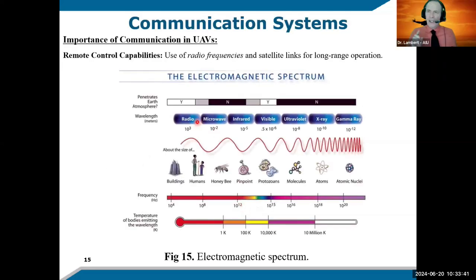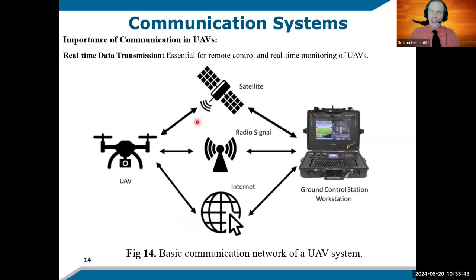Abdullah, a question. How much energy does it take to actually communicate by remote? Well, we cannot define energy with a numeric value here, because different types of drones require different antennas, and those antennas depend on the terrain where you are operating. If it is line of sight or beyond line of sight, the gains of those antennas will be adjusted.